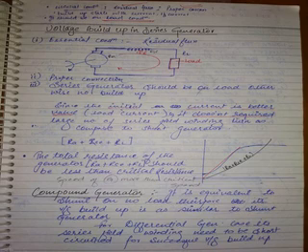So the difference between shunt and series is, a shunt generator's best condition should be on no load. A series generator's best condition should be with some load. Here comes the turns concept. You have written that for a series generator, you require a thick conductor with a smaller number of turns. Why are you making a large number of turns in a shunt generator? What is the reason?